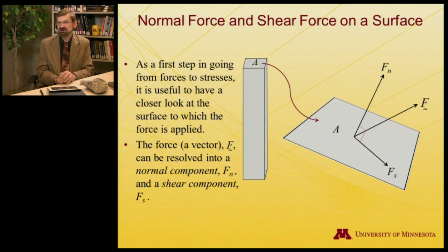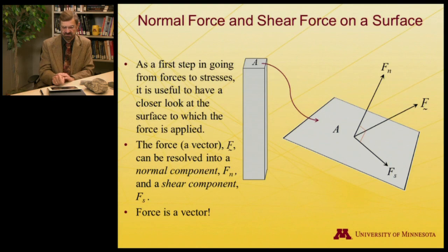And so we see now that the force is a vector. We started out with it pointing up and out of the surface, and that vector can then be resolved into normal and shear components. The important point we want to take away from this is that force is a vector, and when we move from forces to stresses, we want to think about what a stress is. And we'll see, in fact, that stress is a tensor and not a simple vector.